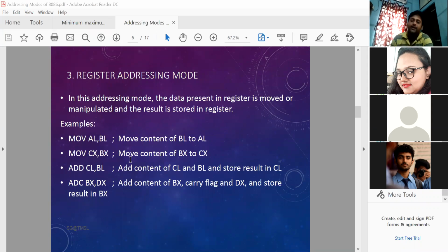Like in the case of 8085, all the arithmetic and logical operations are accumulator oriented, so automatically the result will be stored inside the accumulator, and by default one data byte must be in the accumulator, and the second data byte can be from any register within those 7 programmable registers. But here that is not mandatory. Any register can be added to any other, and any register can be used to store the result.